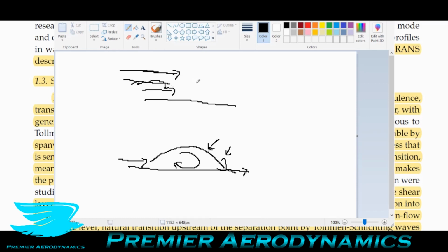What you have is one flow moving faster than the other, so it's going to produce these roll-up parts on this shear layer. What's happening is the flow between these two is mixing, and it's getting ripped apart between these two jets, or technically speaking, one's a jet, one's a wake, but I'll get into that in a second. They're getting ripped between these two different velocities of flow. That means some fluid is being ripped off of the slow fluid and rolling up. That's the Kelvin-Helmholtz instability.